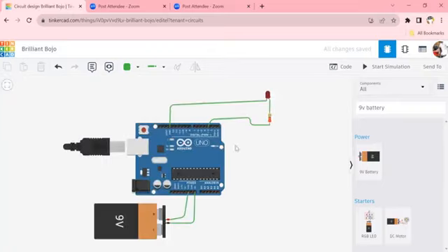No, not there. Good. That's better. Okay. Good. So your connections are fine. Oh, now look at your battery. The positive of your battery was connected to GND. So click on it. Click on that red line. You're supposed to connect the positive side to VIN.